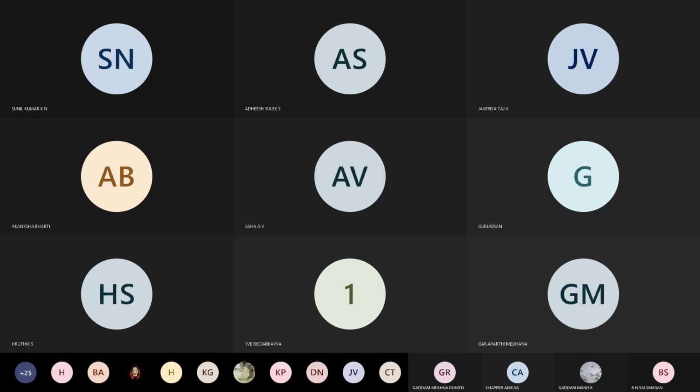So this is the averaging amplifier, in which RA is equal to RB is equal to RC is equal to R. So the value of RF by R should be equal to 1 by n. Suppose it is equal to 1 by n, then as you know, it is nothing but an inverting summing amplifier. So what will you be getting?